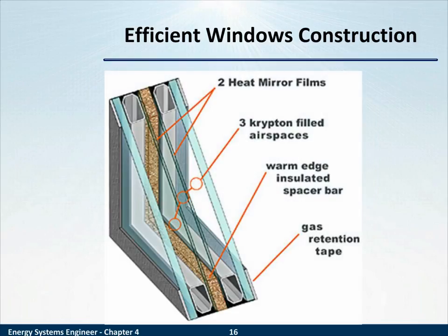This next picture is an example of the suspended film we talked about. In this case, there are two films suspended between these two panes of glass. This is called a quad glass or super glass. And indeed, with this dual pane window and 2 suspended films that have a special coating on them, you can get windows that perform as insulation as efficiently as a 2x4 stud wall.